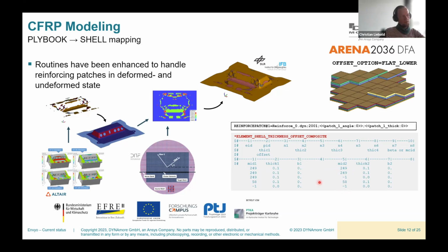So we have the same number of integration points through all of our parts, but at some point there's just no material available, so we support how LS-DYNA is considering that. And we can also introduce the influence of the sensor band with the clustering method, where a dedicated material ID is assigned to the integration point where the sensor band is found.